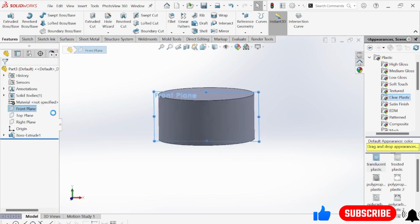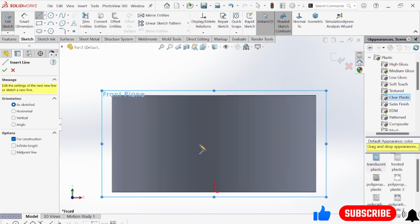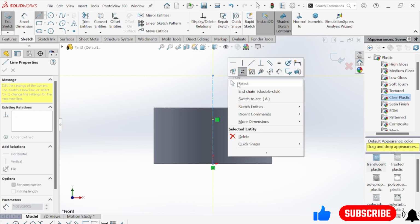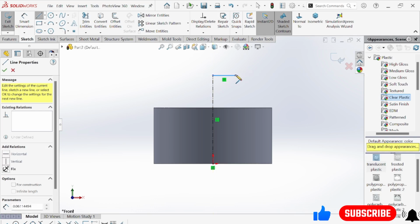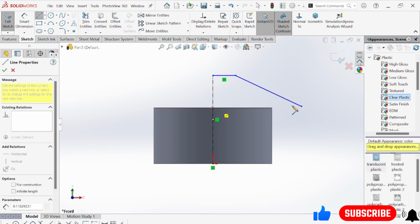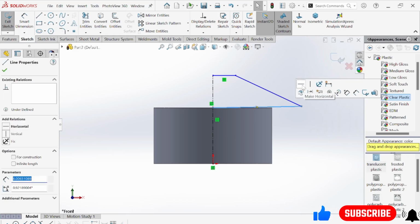Come here. Select the front plane. Now here you see, again, we need to make a part which we can use as a connector, right? We call it a connector in engineering. So just come here and make a profile like this. Make this one horizontal.